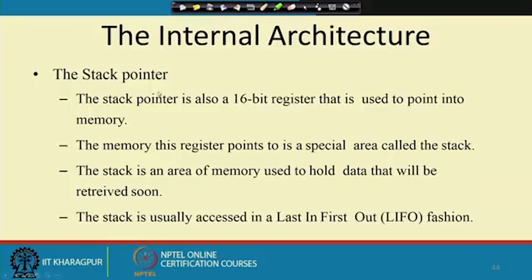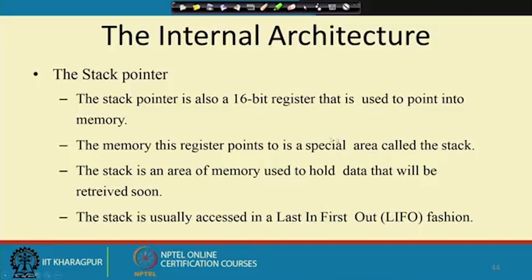Another very interesting register is the stack pointer. This is also a 16 bit register, and it points to a particular position in memory, a special area called the stack. This is an area of memory to hold data that will be retrieved soon, and it works in a last in first out fashion. We will come back to this stack later. For the time being, we just understand that the stack pointer is another 16 bit register that points to a special portion of memory called the stack.